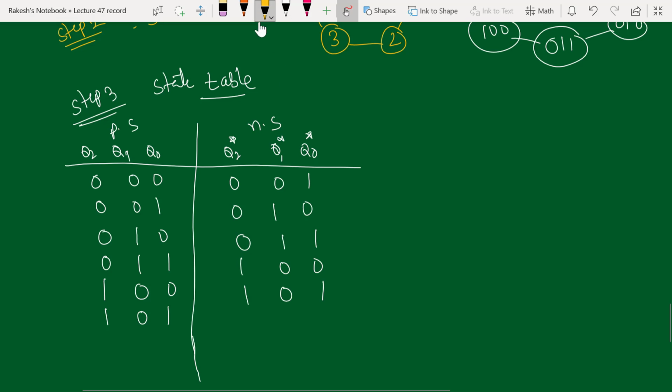Now here is the interesting point. Whenever it encounters 5, the next state is supposed to be 0 0 0. We are not making it go through the 6 transition this time. See, in the first design we said that the counter momentarily goes to 1 1 0, then it resets to all zeros. But in this case we are directly making it go from 5 to 0 0 0. Similarly, when it encounters 1 1 0 also, we are making it go to all zeros. Similarly, if all ones comes also, we are asking the counter to go to all 0 states.